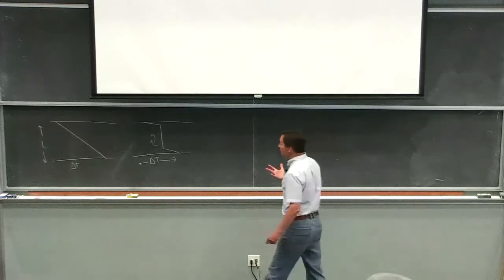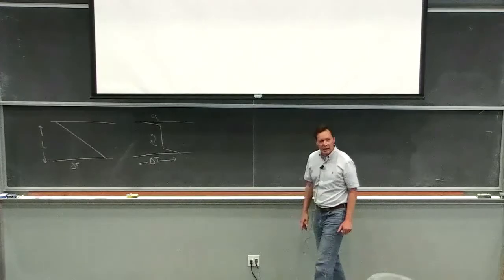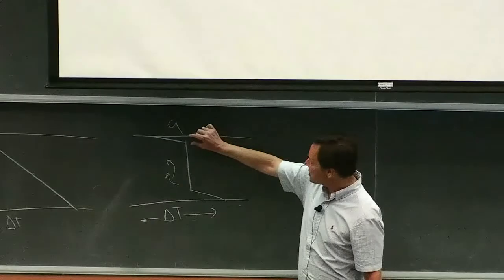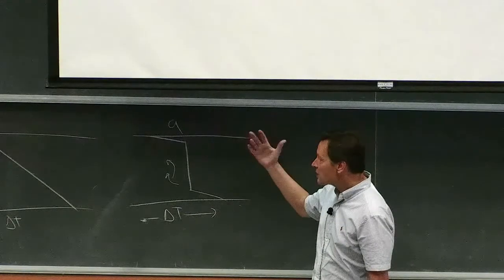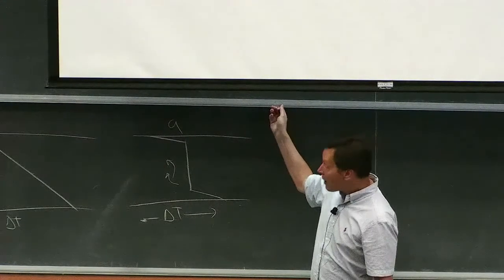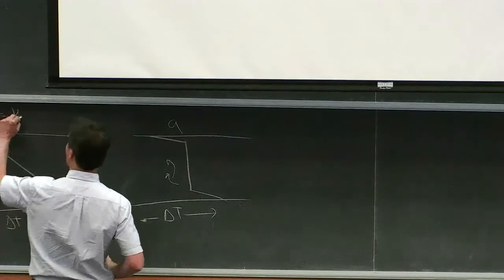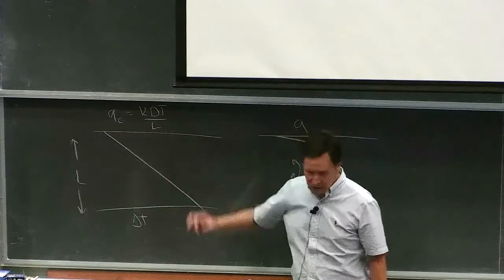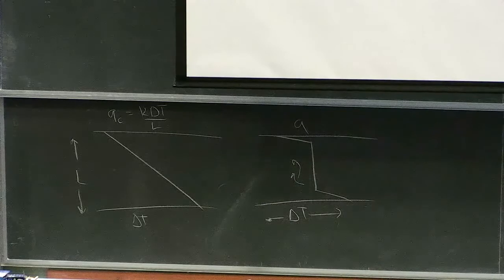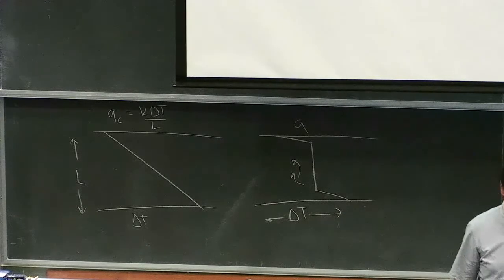And in some ways, thinking about the heat transport in a convecting fluid is really all about thinking what are the processes that are going on in setting the thickness of that layer? This approach or theory is sometimes described as boundary layer theory. We know that if we were in this state, the temperature that we would conduct out along this temperature profile would be essentially this. And so convection, in essence, gives us a way of cooling the planet much more vigorously than we would be able to if convection wasn't possible.